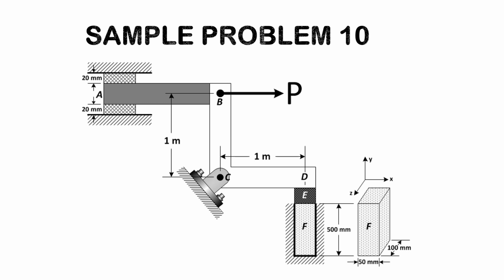Assuming that the normal force in member AB is P outright neglects all the other structures that are connected to AB, like the rubber pads, and of course, since BCD is connected to the bar F and the switch E, it also neglects those forces as well as the pin. So do not assume that the normal force in AB is P.